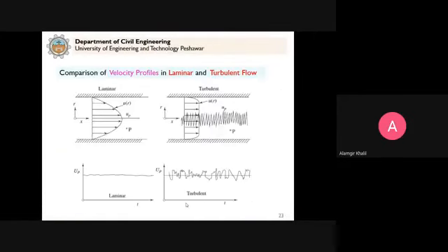So now the comparison of the two velocity profiles. You can see here that in case of laminar flow, we can essentially treat the velocity as moving in one dimension. But in case of turbulent flow, you see that there are fluctuations because of the turbulence in all the 3 directions. So essentially the velocity profile is shown like this. Clear? You can see here. This is how the velocity will occur, and we can model it to be represented by this logarithmic velocity profile.